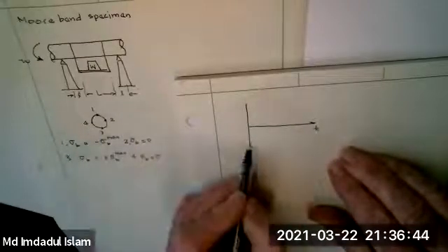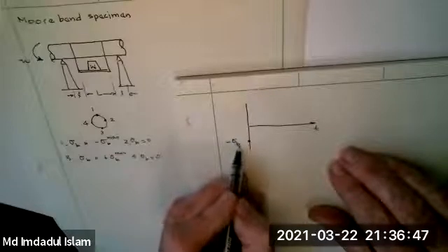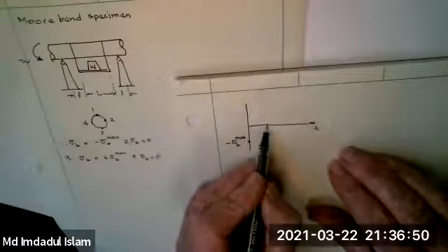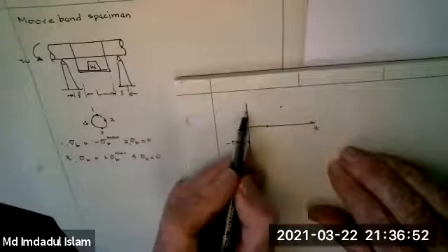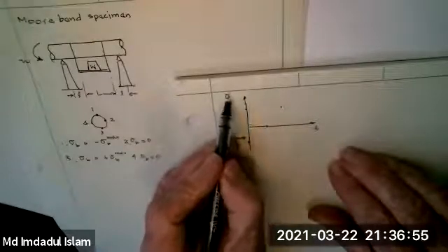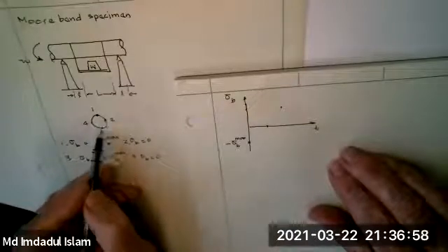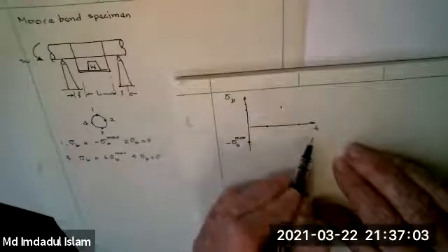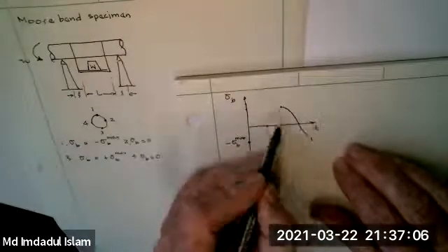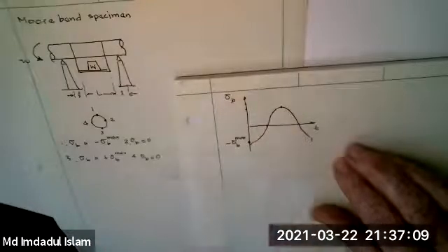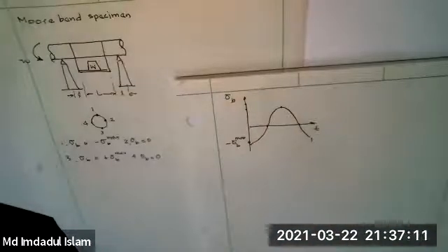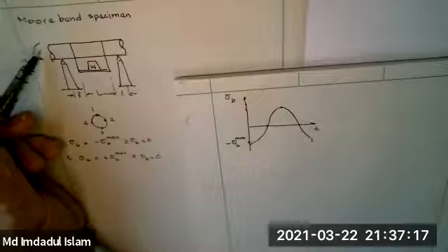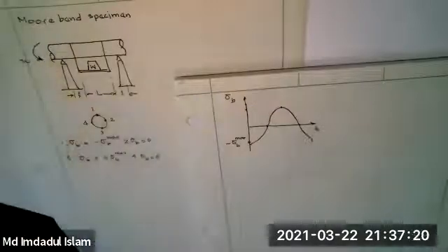So it started off here. Then it went to there. Then it went to plus sigma B max. There's a given point on the shaft now, moving around here. This is what it's experiencing, and back to 0, and so on. Okay. And this is a test specimen, but this is exactly what happens in practice in mechanical engineering. If you put a torque on this thing here, that'll be constant. Okay. Now, you could vary the torque as you load it up and load it down. There'd be a few variations.